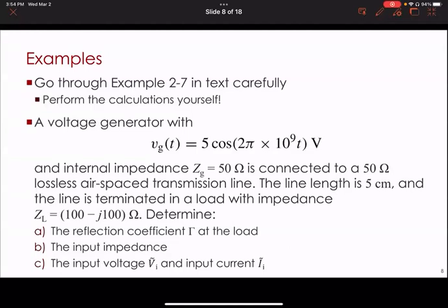This, which I let you think about the last time, came up when we wanted to calculate beta for the input impedance. And we said, well, what's beta? There are different formulas for beta. One of them is 2 pi over lambda. Then you could say, all right, what's lambda? A formula for lambda that you might remember is u_p over f, but then we need f, right? So when you see anything in that form, it's always omega t. And just always remember that omega equals 2 pi f, and so you just solve that for f. We said omega is 2 pi times 10 to the 9. So to solve for f, it'd be omega divided by 2 pi. That's nice, isn't it? The 2 pi's cancel out. We're just left with 10 to the 9, which is 1 gigahertz.